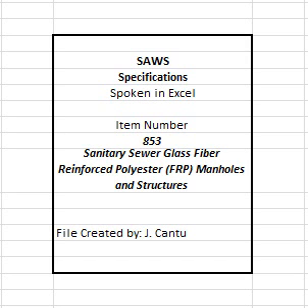853.4 Materials. All constructed FRP manholes and structures shall be watertight. Sewer manhole ring and cover castings, HDPE throat rings, and miscellaneous specifications and details shall meet the current requirements of AASHTO designation M306-10 and specification item number 852, sanitary sewer manholes. See Drawing Series DD852. 1. FRP manholes and structures. All manholes and structures shall be watertight.